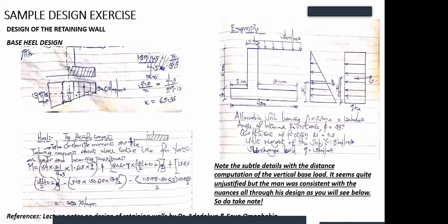Once you know that you are only considering what? The pressure you are considering is just from the minimum up to the center. This is the trapezium. You can split this trapezium into two. You have a rectangle up and a triangle down. So this rectangle, you can easily take the area of the rectangle. The height of the rectangle is 50.63 times 3.3. 3.3 is the base of the rectangle.